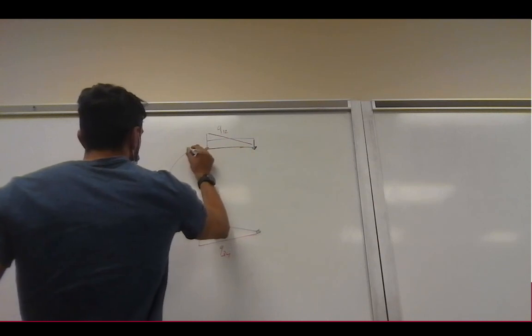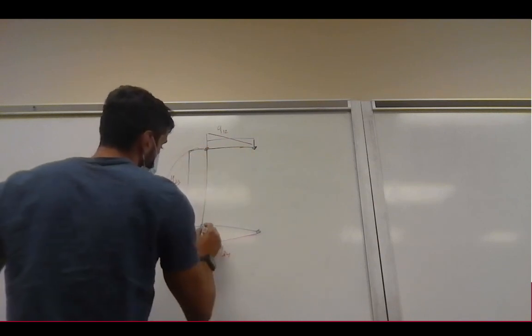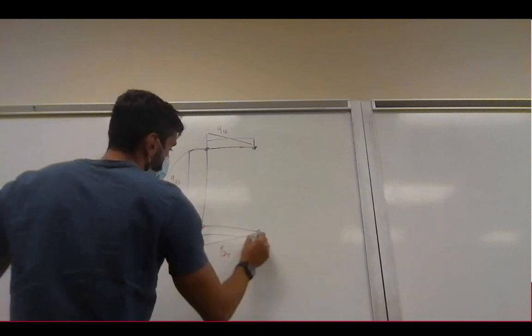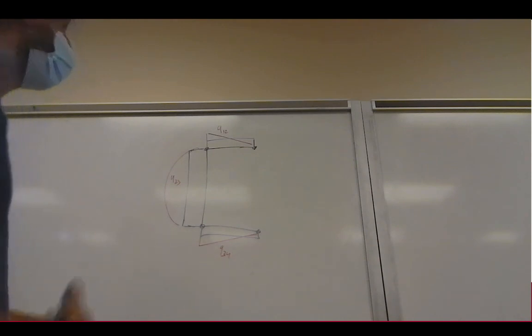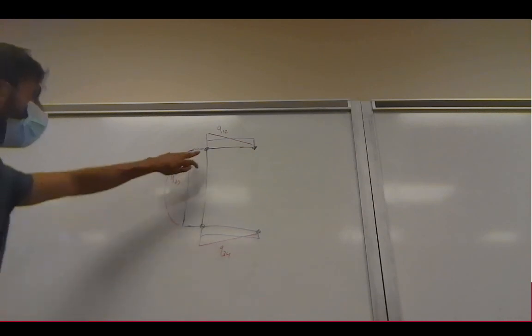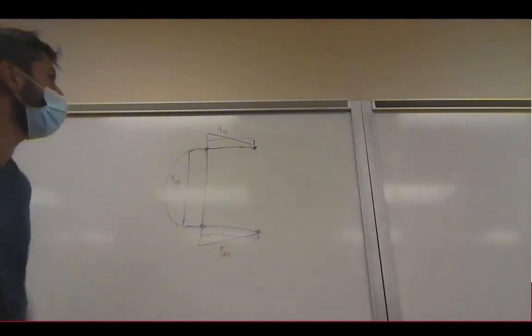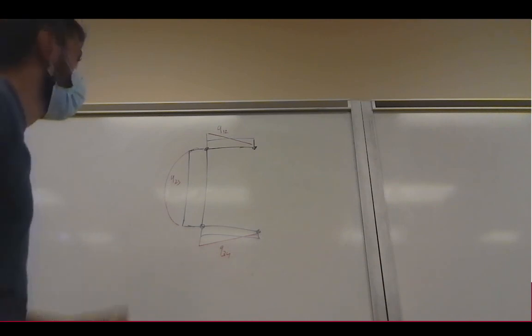When we cross the second boom, we add some additional shear flow to it, and we cross the third boom. In this case, we'll go down again. As you can see, the blue line and the red line don't match because we have made a simplification and assumed that between two booms the shear flow is constant. Would you ask us to calculate the boom areas, or do you just provide them? It depends. Sometimes yes, sometimes no.